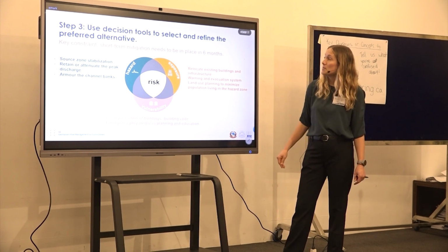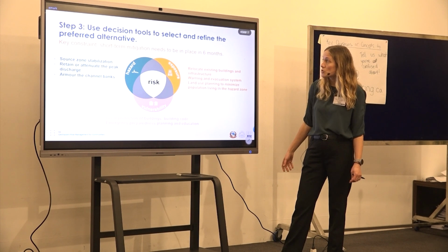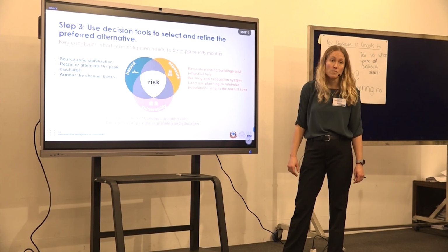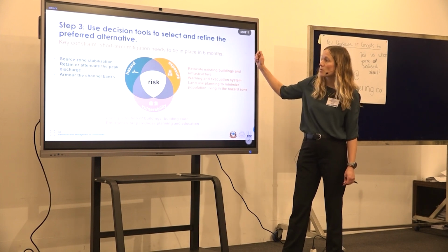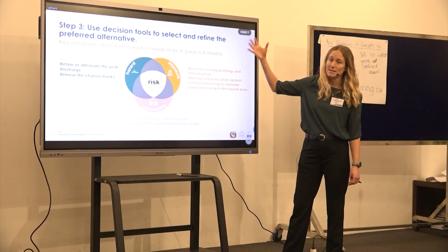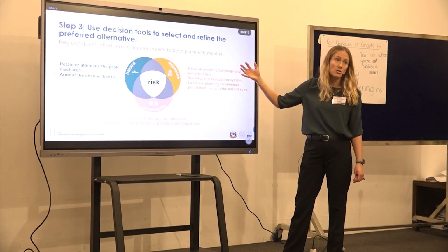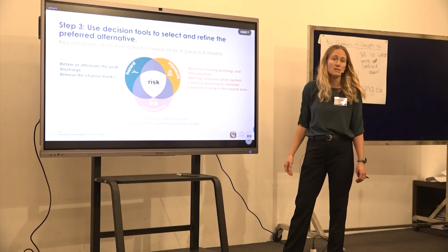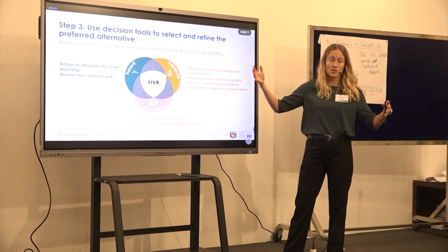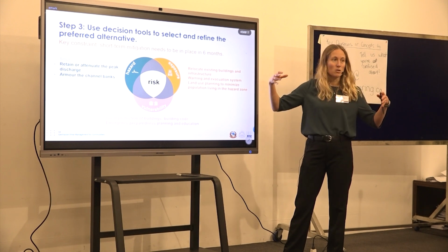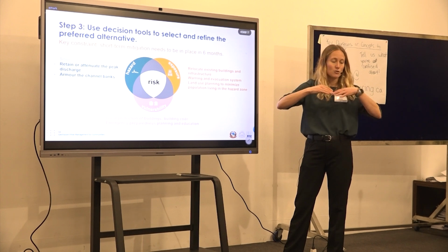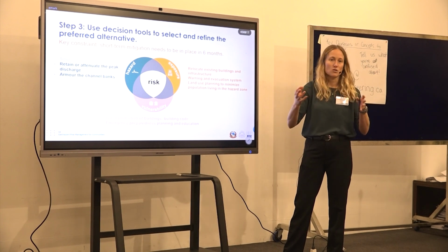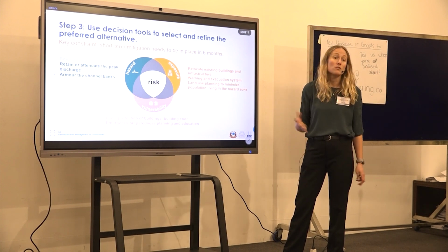And then the next step here is to use decision tools to select a preferred alternative. As I said, the key constraint was that short-term mitigation needed to be in place in 6 months. So pretty quickly, we can start ruling things out. We can't stabilize the source zone here. This watershed, although still much smaller than many of the sites you're dealing with in the Himalayas, is still a large watershed in the Rocky Mountains. They're limestone, and there's no trees. It's all just scree and rocks, and there's so much material, so you just couldn't conceivably get up there. There's no access as well.